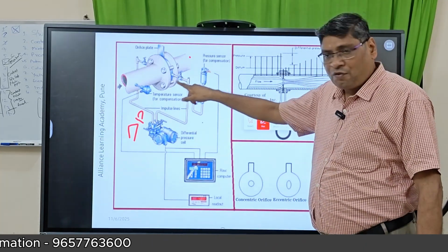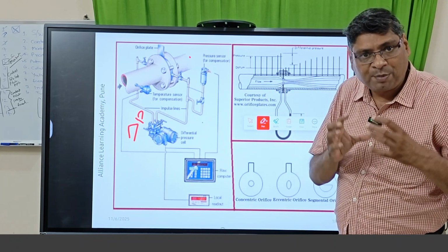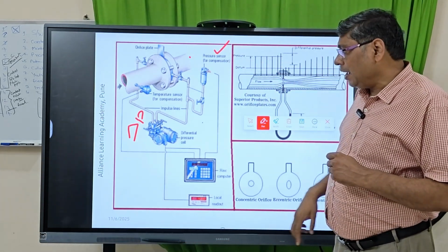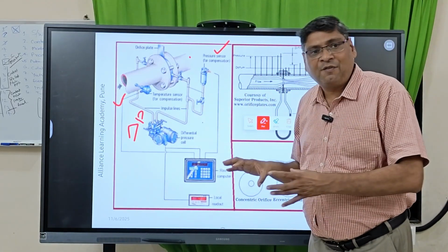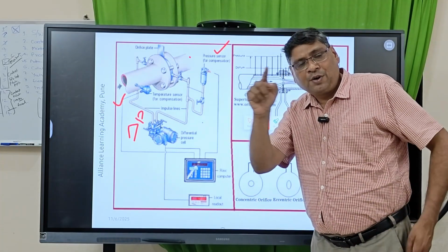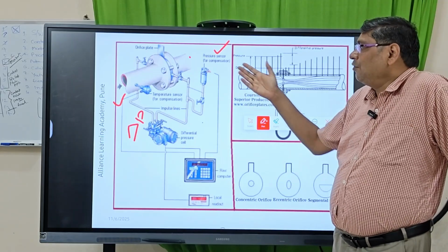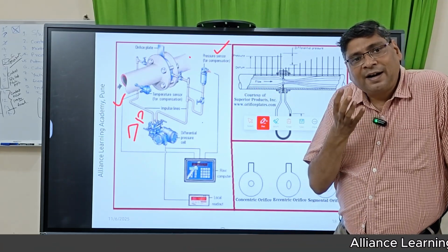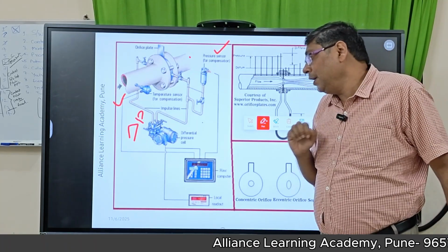So with this orifice plate, or delta P type flow meter, we are first measuring delta P, and simultaneously we are measuring pressure and also temperature. All this data will go to the flow computer, and we do the square rooting. I will tell you the meaning of square rooting later, and then we do this density compensation to get the correct flow. So with Nm cube per hour, N is an important term.